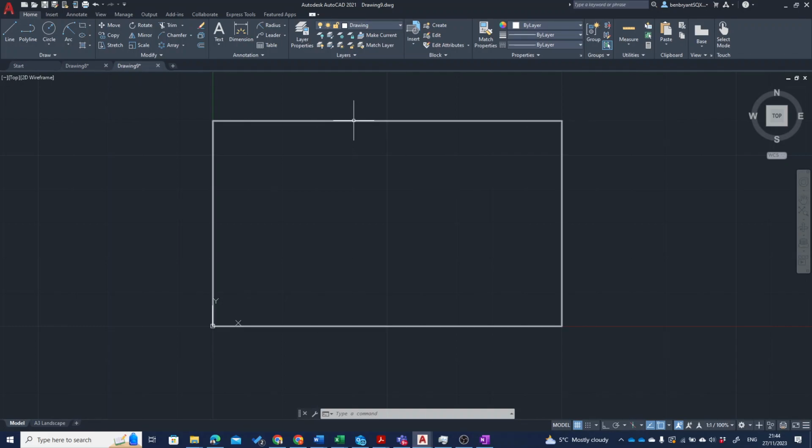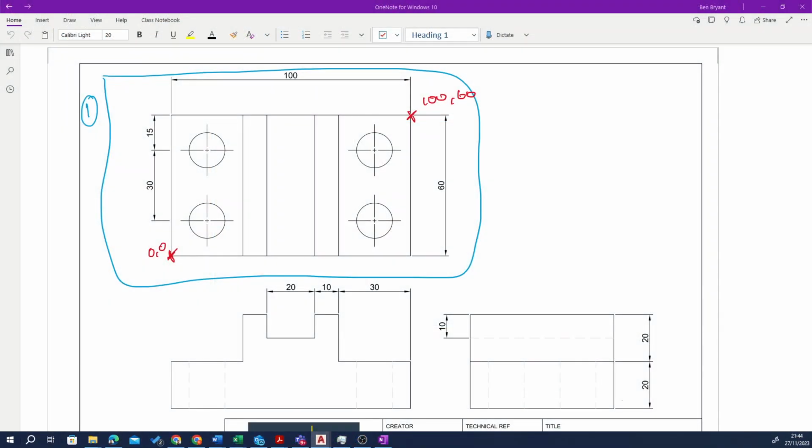So what I'm going to need to do is I want to break this drawing down, really, is that it does have 2 lines of symmetry. So there's a line through the middle across the x-axis. There's a line through the middle under the y-axis. So to make my life easier, what I'm actually going to do is only draw this section here. So I'm going to draw one circle. I'm going to start to draw some of the lines and mirror this around.